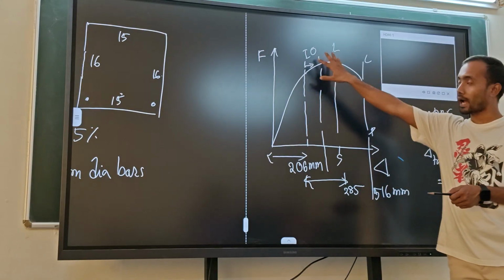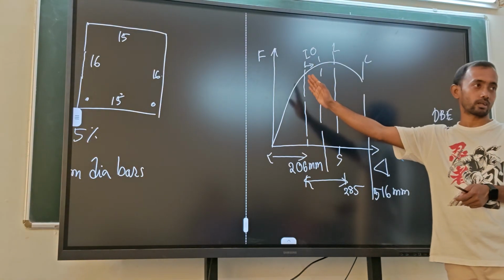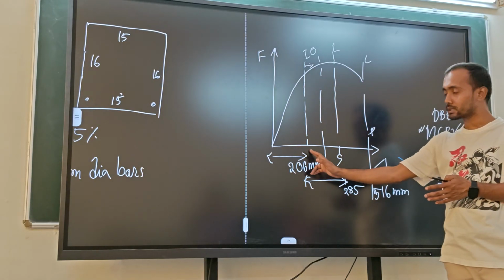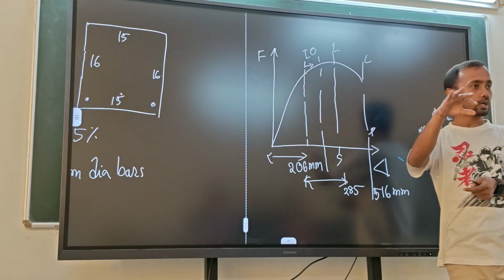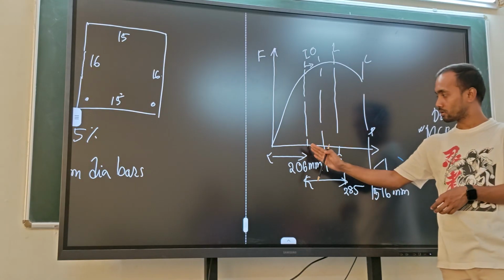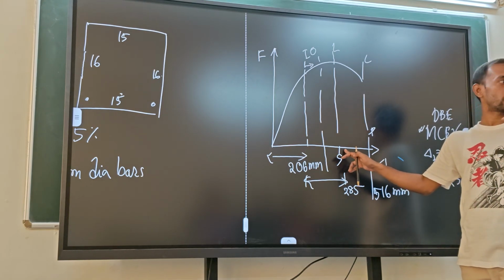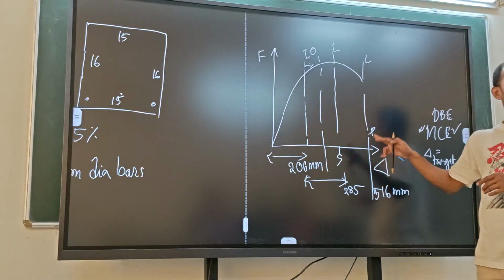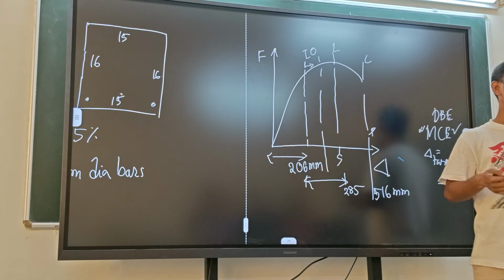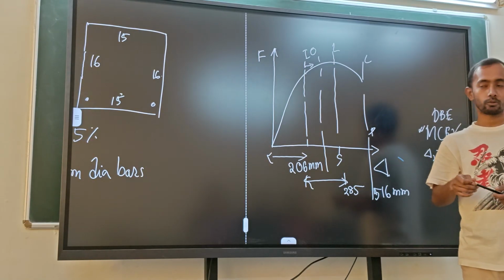So that's why there are three levels. IO doesn't define the failure of the structure. IO means safety. When the first beam fails, meaning the first beam reaches the IO, it is hitting you now and it is going to damage. So it is better to know. This is IO of the first beam, then this is LS of the first beam, and this is CP of the first beam. Whenever you get an indication, you have to take a decision immediately. You will not wait for the next member to give another indication.